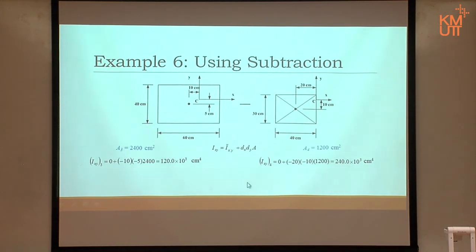And then you have the 2. Again, that one minus that one, in this picture, turns out minus. Now, because it's not x squared or y squared, it's x times y, there is no guarantee that it will always be positive. Ix and Iy have to be positive, right? Because it's x squared, y squared, and dA is always a positive area.